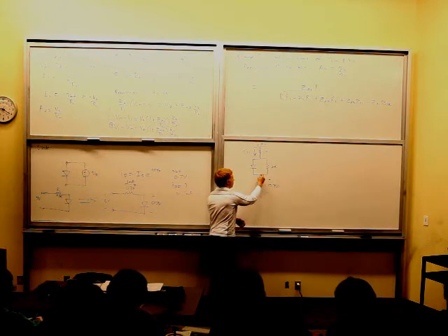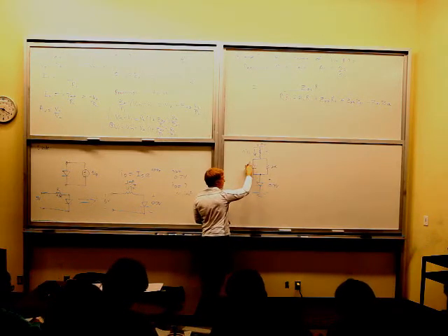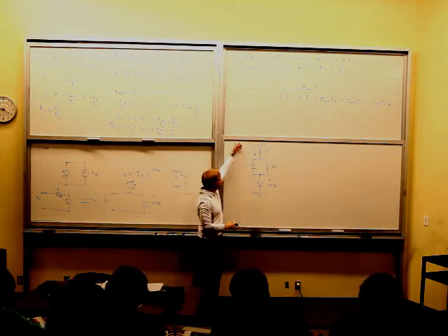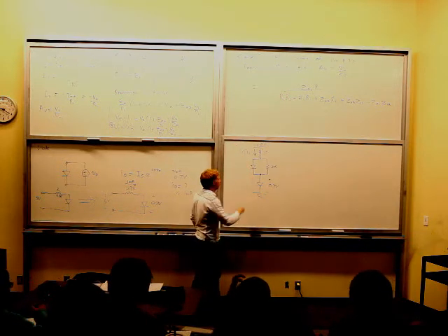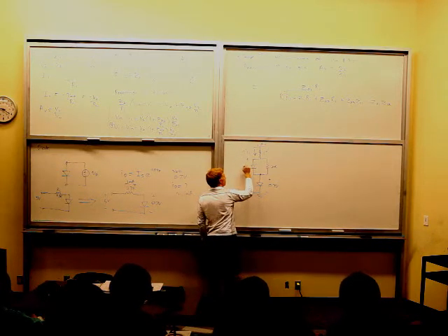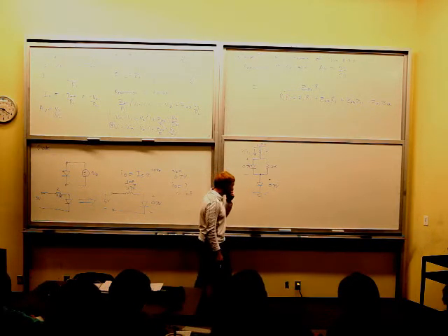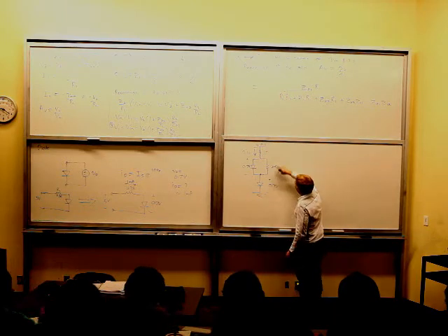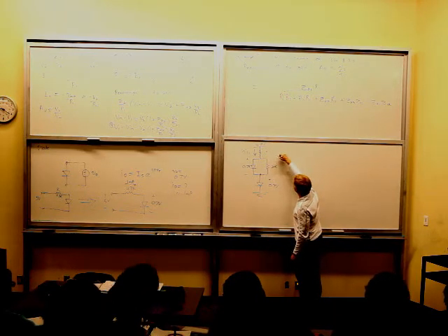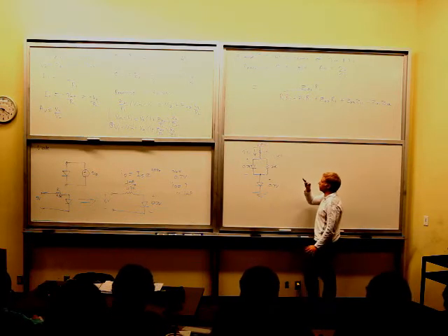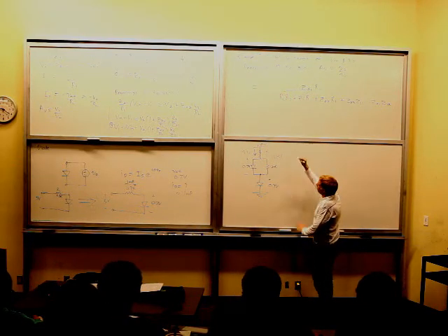So that means that this node here is 0.7 volts. Then this diode, I'm going to assume is forward biased, which makes sense because we've got a pretty high voltage here. So we should have enough voltage for 0.7 here and 0.7 here. I'm going to assume that this one is forward biased at 0.7 volts. So what does that tell me? That tells me that this node voltage up here must be 0.7 plus 0.7 is 1.4 volts. And that's completely sufficient to specify the problem here.